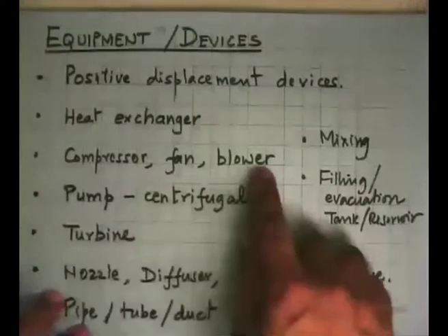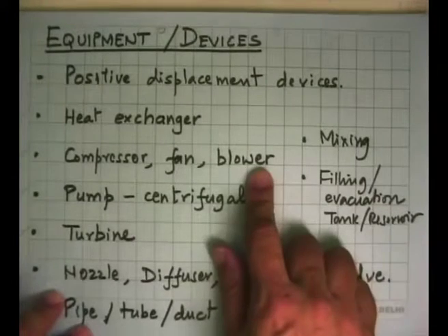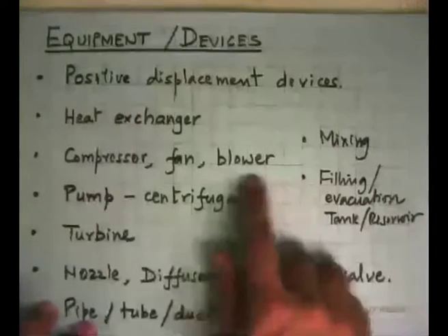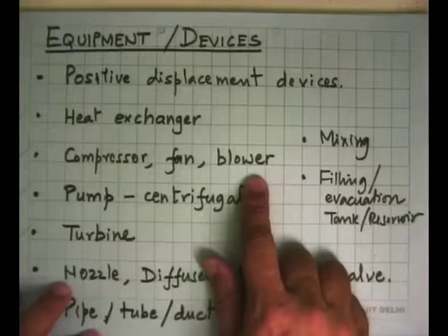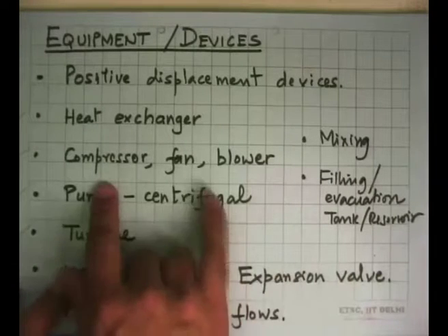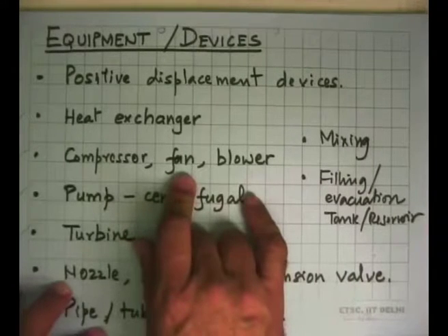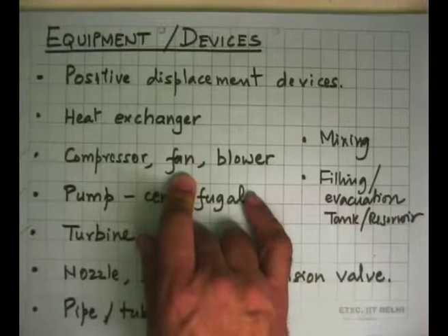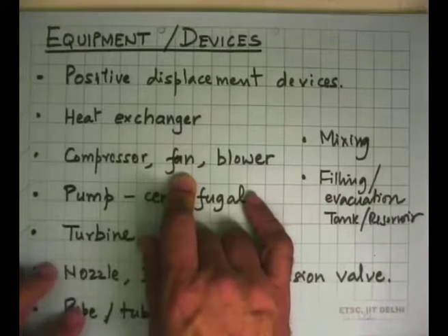And both these, we said, are work input devices, and in the ideal case this would be at best isentropic. And we also saw that the way we get these machines, we do not add heat into these devices. In reality, if it is running above a temperature, there will be a little bit of heat loss from the surface to the ambient air.